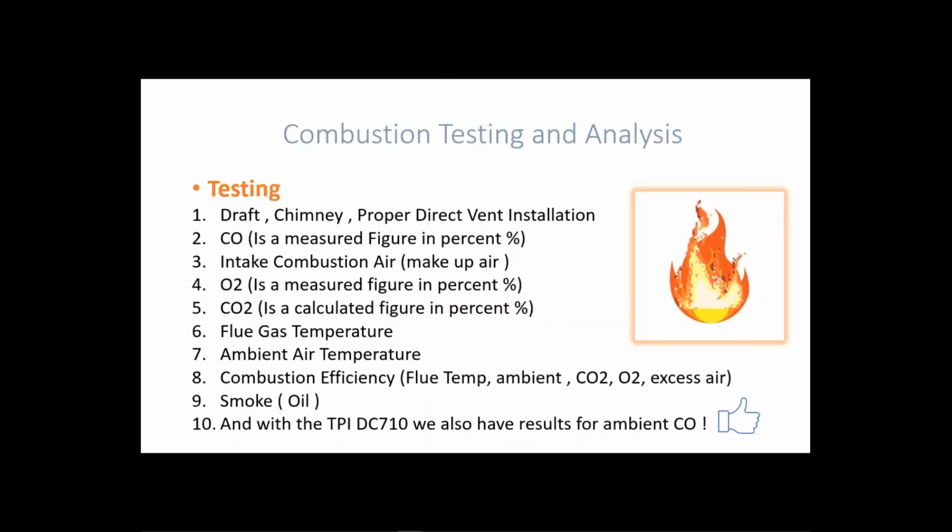So for combustion testing and analysis, for the testing part, we need to know the draft. Are we going to measure that draft? Well, on modern heating equipment, it's important to know that the draft is proper, especially on direct vent systems. Chimneys, and there it is, proper direct vent installation.